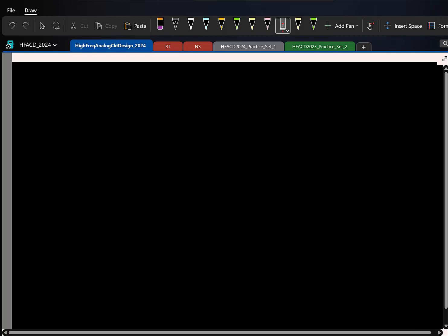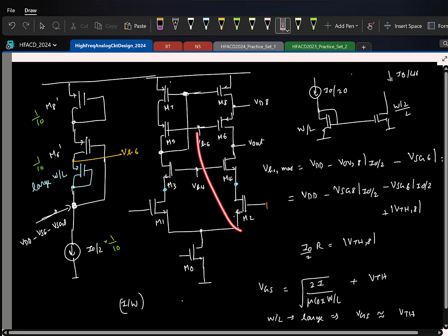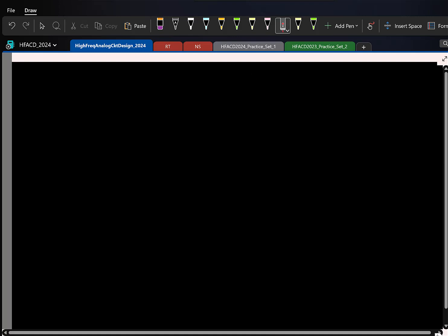Cool. So next let's look at a variant of this cascode, right? And again we'll start with the single-ended version and then we'll construct the differential. So in the telescopic cascode we had an NMOS transistor to which we applied the small signal, let us say delta V, and this converted the voltage to a current, and this current was buffered by an NMOS common gate, and at the top we had a cascode current source using PMOS, and then we did this, right?